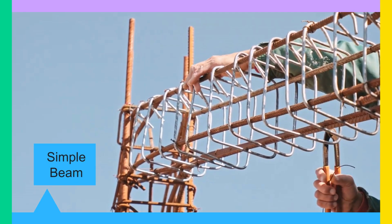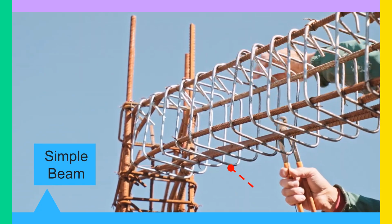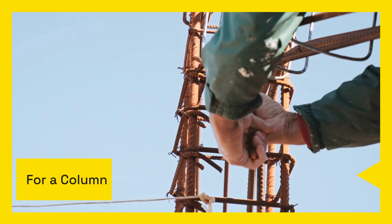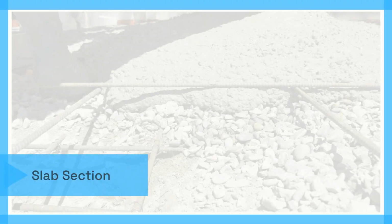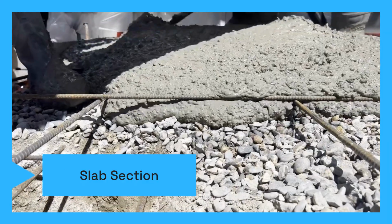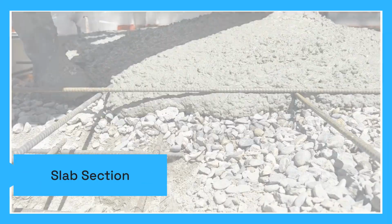When scheduling for a simple beam, you'll use straight bars for main reinforcement and stirrups to resist shear forces. For columns, vertical bars are scheduled using shape 00, and links, such as shape 51, are scheduled to confine the concrete and prevent buckling of the vertical bars. In slab sections, reinforcement is typically scheduled as straight bars or mesh, depending on the design. The schedules define the size, spacing, and location of these bars.